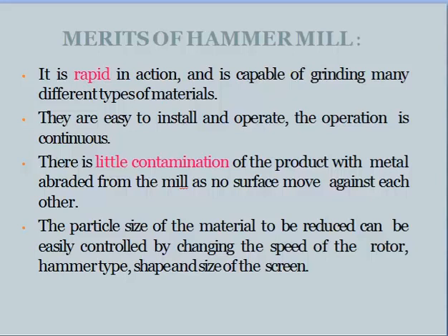The particle size of material to be reduced can easily be controlled by changing the speed of the rotor, hammer type, shape and size of the screen. So, the particle size can be easily controlled by changing the speed of the motor. Due to the change in the speed of motor and hammer type, the impact forces may change, and the desired size and shape can be obtained by controlling the speed. So these are the merits of hammer mill.